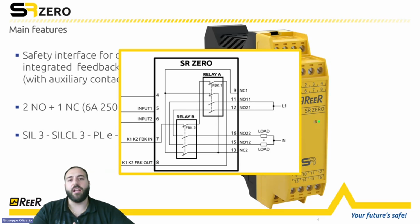In this case, you can connect every safety device with integrated function like EDM or manual reset. On pin number 5 and 6, you have the inputs where you physically connect the OSSD output from the safety device to the safety interface. Plus, you have two normally open contacts plus one normally closed contact. The combination between the safety device in category 4 plus this SR0 is the complete set for a category 4 application.